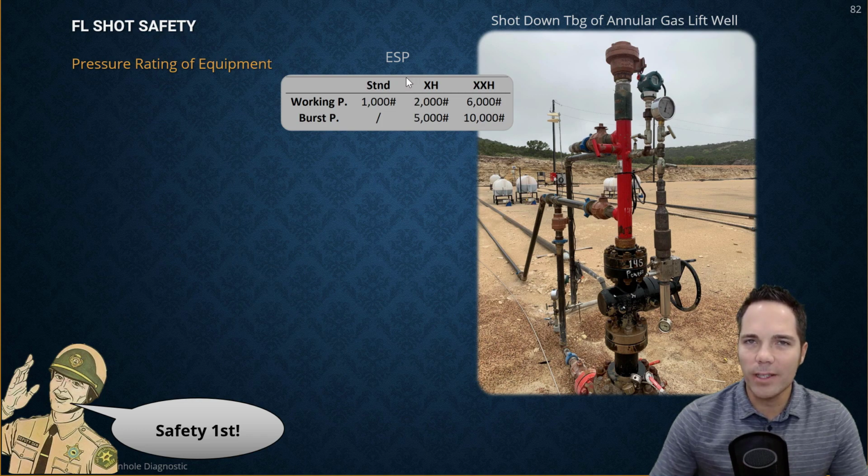And then I opened the casing valve to my gun, and it was hard to open. I eventually got it open, and I could hear the pressure was really high. I looked at the pressure gauge, and it absolutely wrapped around my pressure gauge. I shut the valve and said, oh my gosh, what's going on? Then I found out it had 2,200 PSI on the casing, because the casing valve was closed.